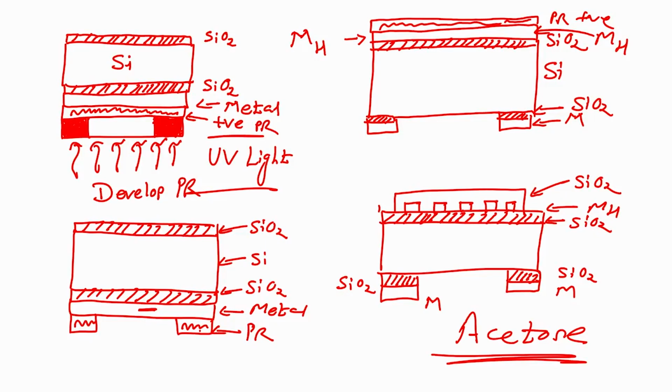This is my second mask, and then I can protect the contact area somewhere; I cannot grow insulator on that area. So, that is fine. On this insulator, we can deposit another metal. On insulator we are depositing another metal, this metal is for interdigitated electrodes. After depositing this metal, we will spin coat, once again we have to do the same process, we